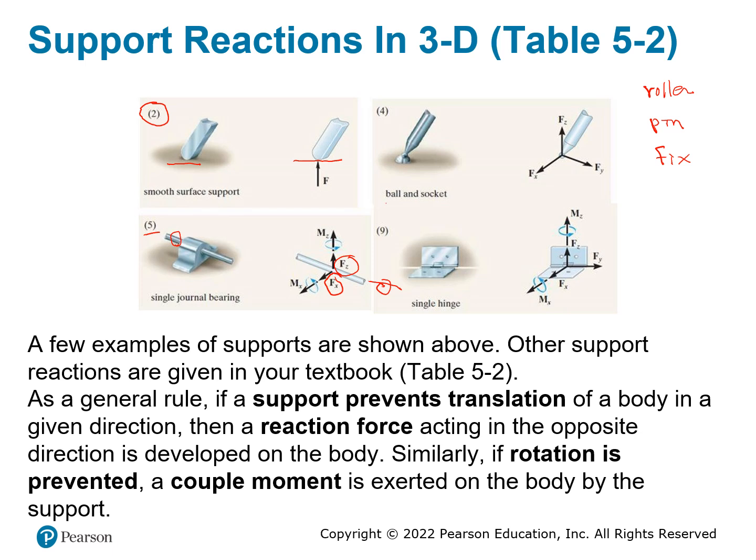Here is a ball and socket, which is the case we just showed you with a picture, the yellow-colored big ball. We said this allows the device to rotate with a maximum angle, so you can freely rotate in any direction. However, you cannot leave the socket, so there are supporting forces Fx, Fy, and Fz. You have 3 unknowns.